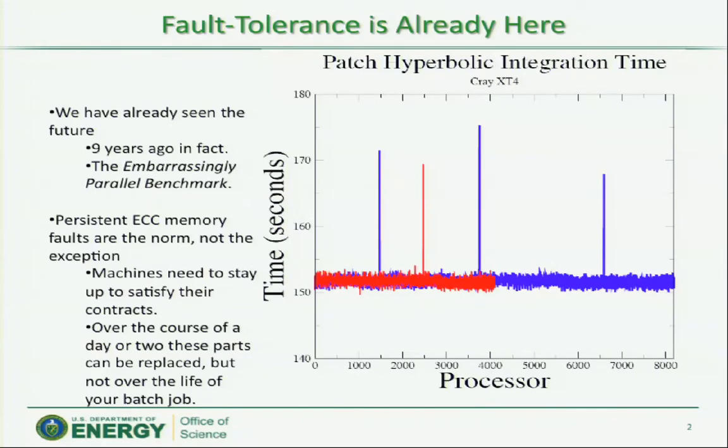And these big spikes are the result of persistent DRAM failures on the machine that don't stop your job from running. So what's happening is that your memory, I'm not sure if you know how your computers are made up, but your bytes or your words aren't on individual DRAM chips. Your memory is banked, so each bit is sitting on a different DRAM chip, and that gives you lots of bandwidth. As you load a word, every DRAM chip can grab its bit, put it on the bus, and off it goes. So there's your big bandwidth, all for the same latency.